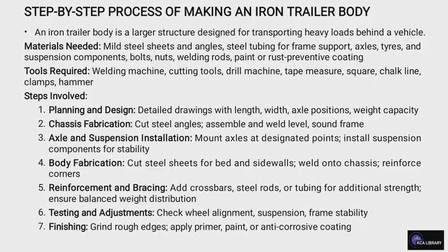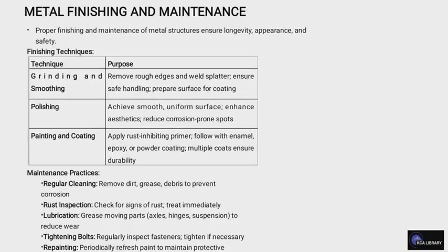Next is the body fabrication, where you cut steel sheet for the bed and side walls, and also reinforcement and bracing, which is hardened crossbar, steel rod, and the likes. And the next is testing and adjustment, and the last step is finishing, where you grind rough edges, apply primer, paint, or anti-corrosive coating.